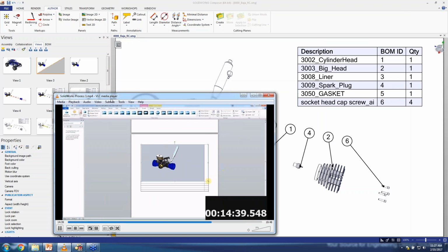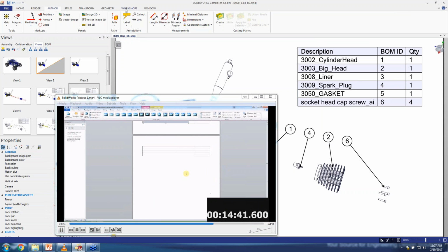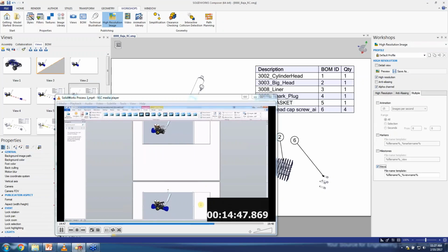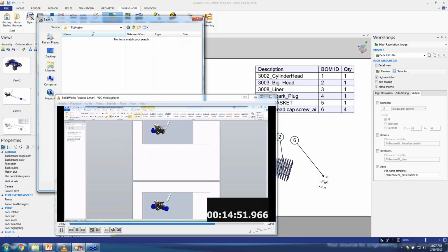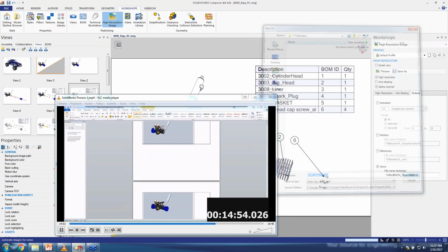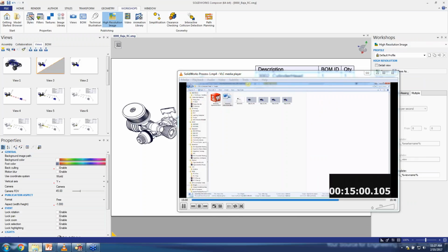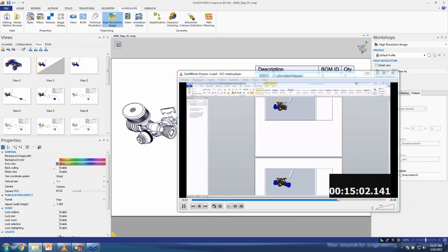that when I take File from Composer, I'm going to go ahead and save out all those images. So we'll say, yep, let's do high quality, let's do multiple, and we're going to save out every single one that you see on the left here. And I'll save those. I've got a publication folder, yep, right there. And it pushes out every single one. You'll see the status down here. I can't even talk fast enough before it's done.